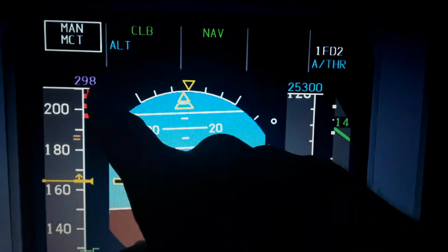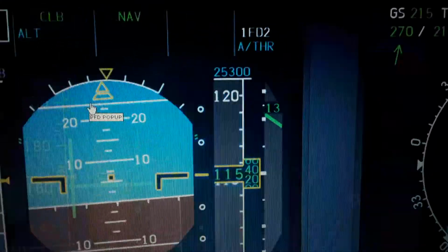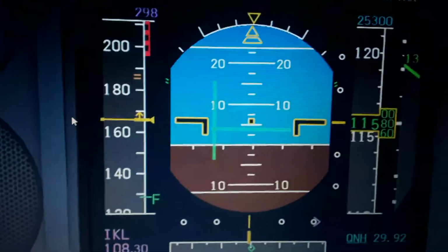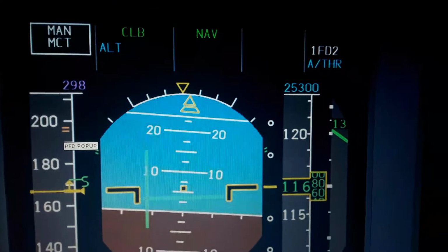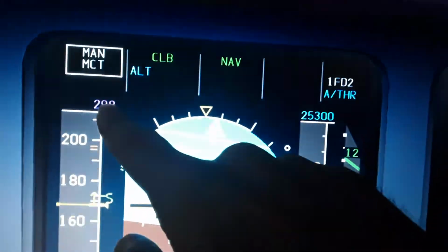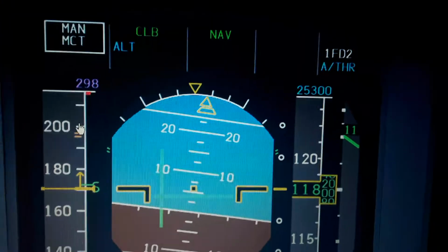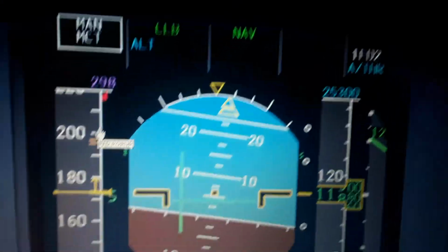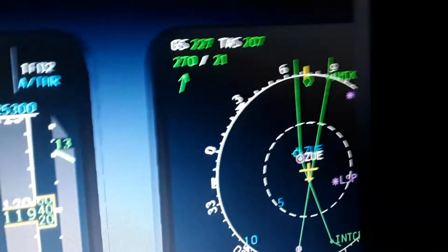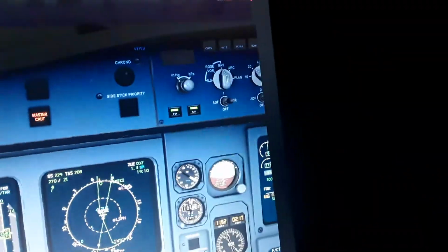And here you can see the upper limit for the airspeed because I have the flaps extended right now. I'm going to retract the flaps maybe, so we're going to have more margin for airspeed. And this is managed by the autopilot and the flight management and guidance computer. This displayed in purple is the managed speed, 298 knots. It's quite high, it's okay for this flight. Maybe I can use it higher, like 340 knots.